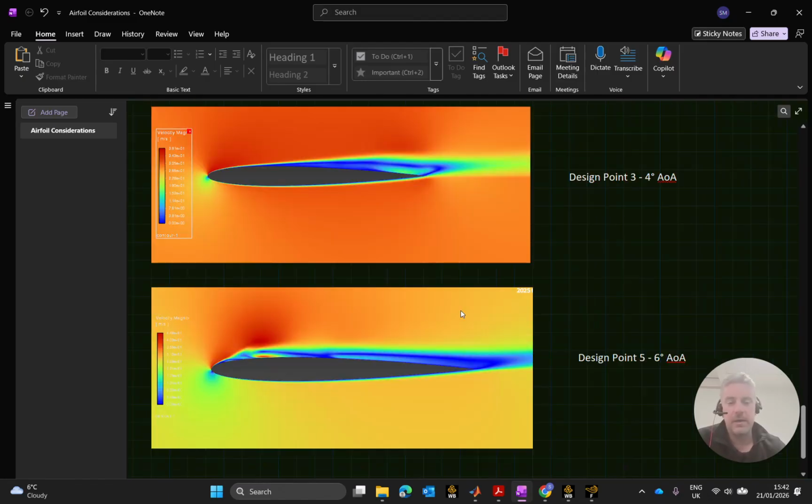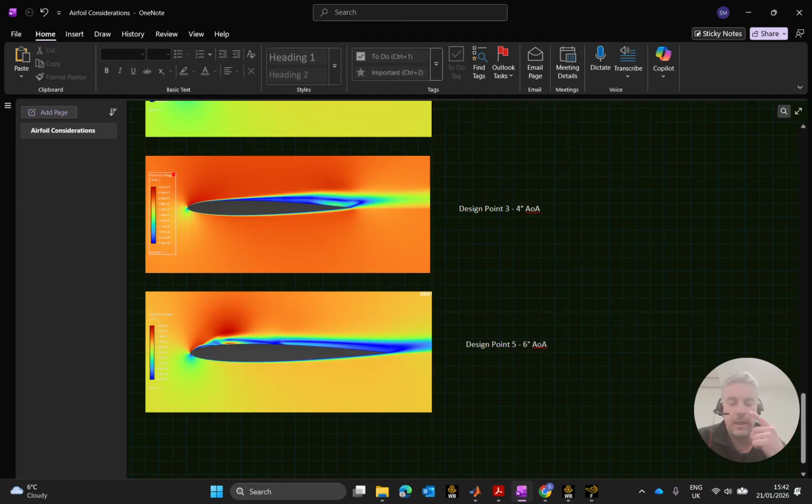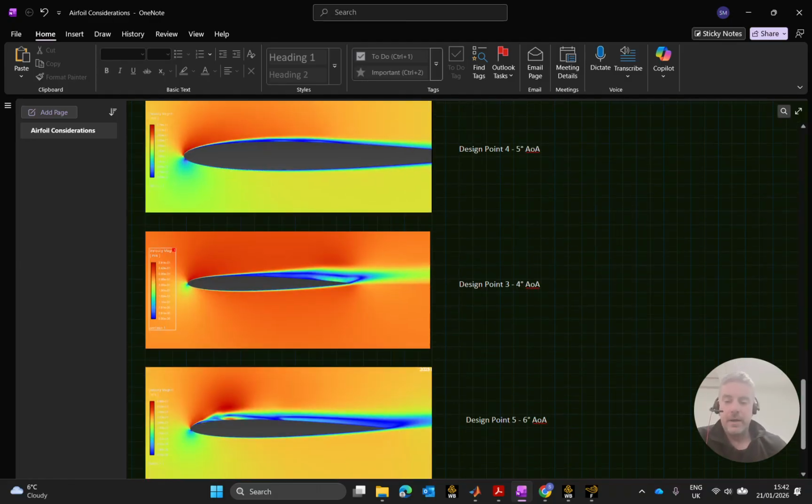There's a huge amount of study done on airfoils, not so much on the NACA 0009 that I have seen, but definitely the 0012 for laminar separation bubbles at certain Reynolds numbers. It is at these low speed Reynolds numbers where the kinetic energy in the free stream airflow can't keep up with the airfoil, if you like. So yeah, there you are.